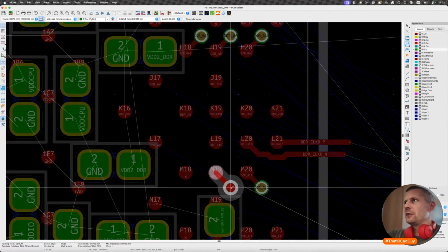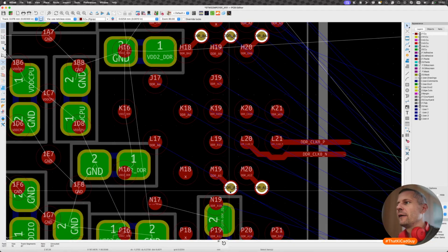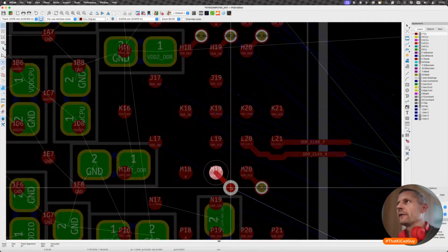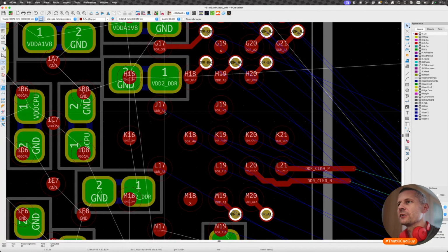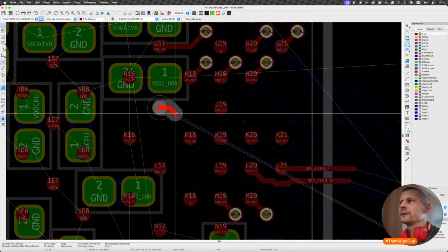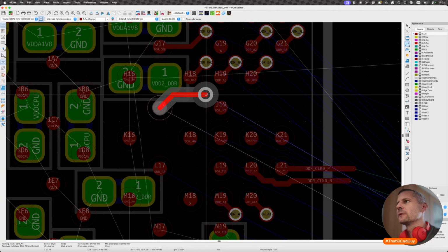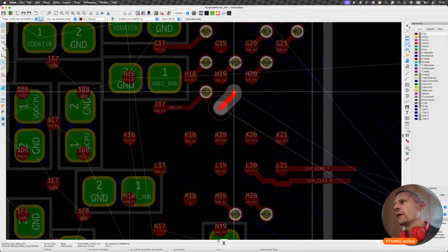I'm using, as you can see, the long hairlines for the cursor to align all the vias with the vias at the top. Yeah, here. With this via, I can always align using the long hairlines, which is why I always recommend using thin hairlines, because it helps on multiple levels.